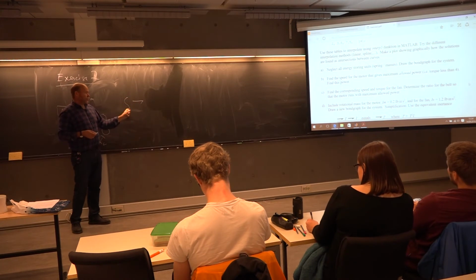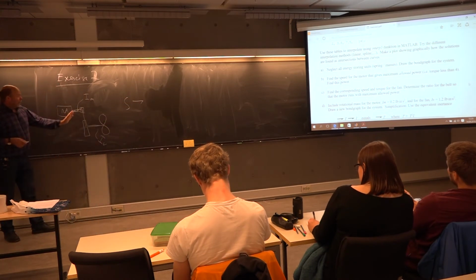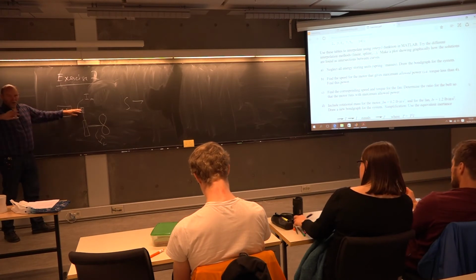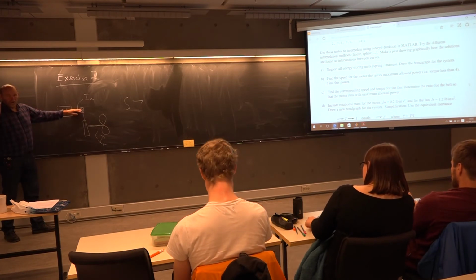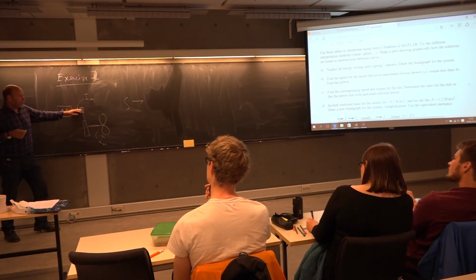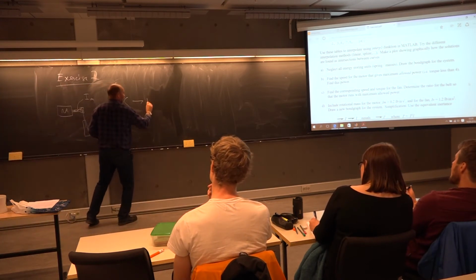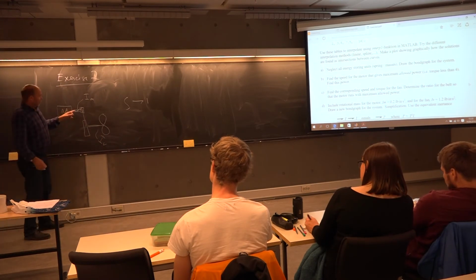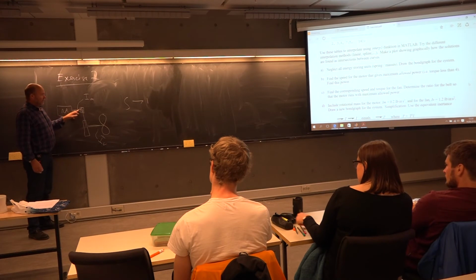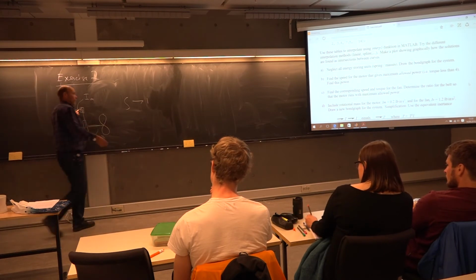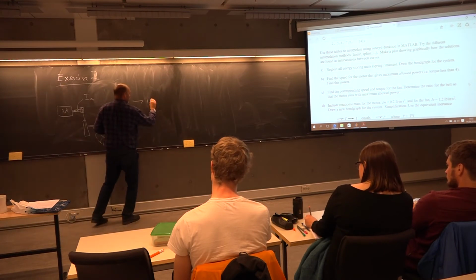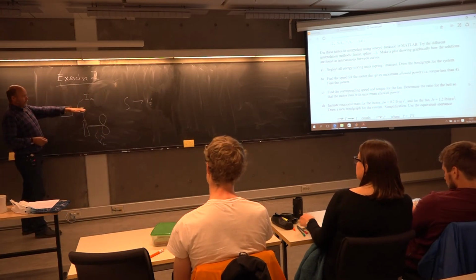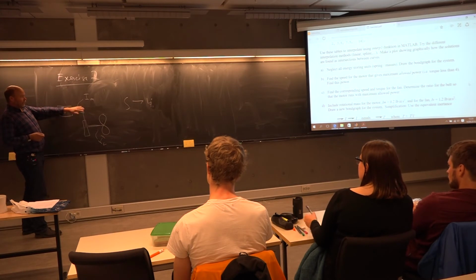And it will now hit something here that rotates with its own velocity, with its own flow. So that's a common flow junction, a one junction. So the rotational speed here, what should we call it? Phi dot number 1, for instance. That is the rotational speed for this part of the problem, just for the motor itself.